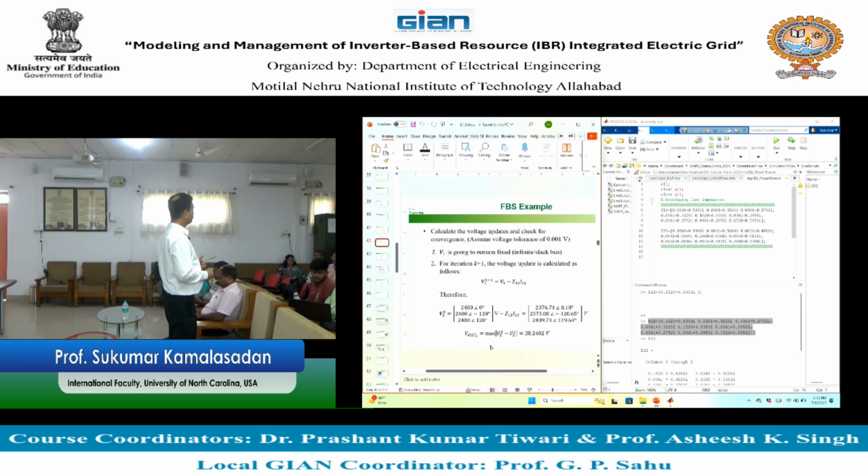So what will you do the next time? We know that we cannot use V21, because V21 minus V22, the error is not zero. So what will you use? We will use V22. And so you use that matrix to update the next voltage.